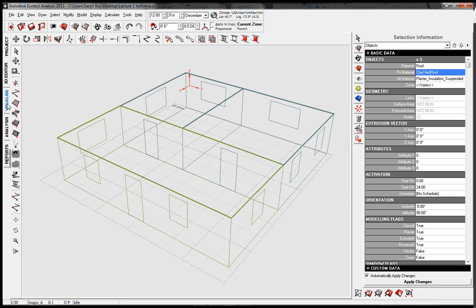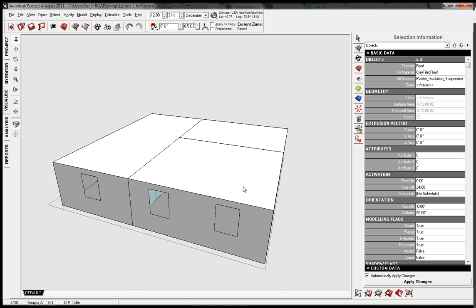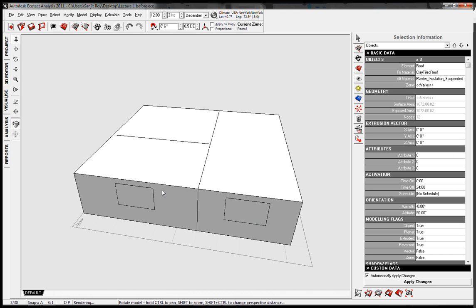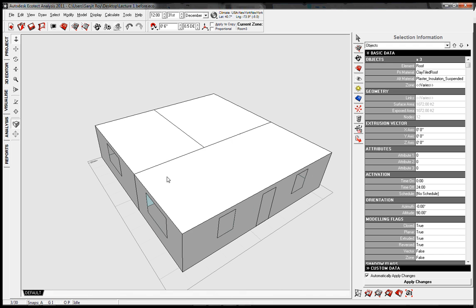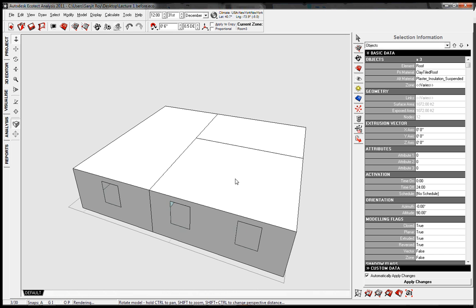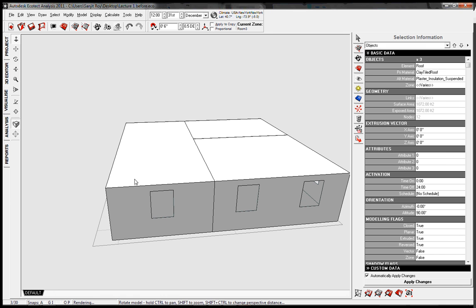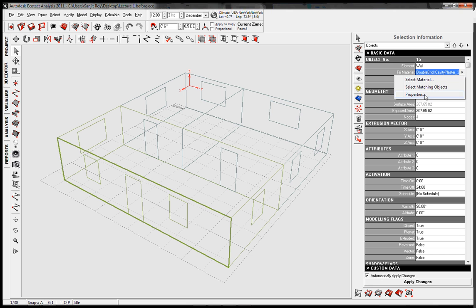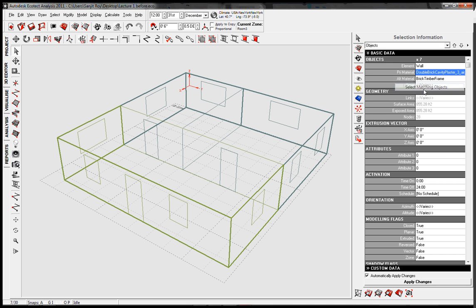Now we're going to click on the Visualize tab to ensure the changes that we just applied have been reflected. And as you can see, the roof that was earlier red in color is now white in color. Now go ahead and change the color of the walls as well. So click on the 3D Editor tab, select a wall, go ahead and click the Primary Material tab, select Matching Objects, which means it would select all the walls.